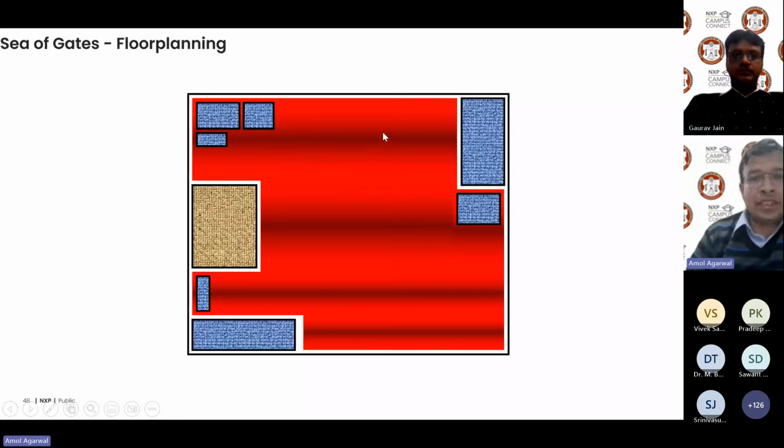You have the RTL, you synthesize it, and then you place it. All those logic gates are depicted here in red color. But along with that, you would have the other hard macros which are coming in. This hard macro also would have some logic gates, or maybe some different logic gates, but suppose it is coming to you as a hardened IP. Say this chip is developed by NXP, but this hard IP or memory could be coming from some other memory vendor, say from ARM or TSMC, from anyone. So this is a hardened IP. You are not synthesizing this logic on your own, but you are using the complete placed netlist or placed GDS for this portion of the logic.